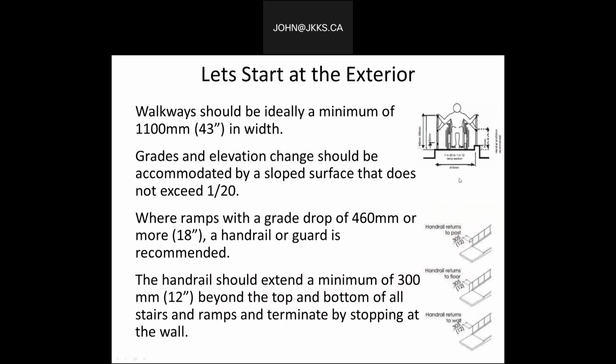If we start from the exterior, we need to consider the pathway to the ramp. It is common in most every home that there will be a grade difference from the grade level or ground level right up to the main entrance door to a home. Exterior pathways should be designed to ensure comfort and safety of all persons, really regardless of age or ability. All pathways should be free of obstacles and provide easy access to the main entry to the house.